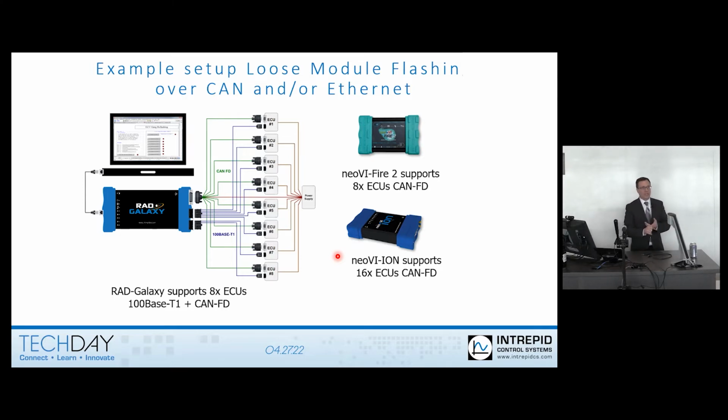So this is usually a case where all those ECUs are the same. You really don't have the ability to put them all on a single CAN bus because they all share a common diagnostic address. So in this case, what we have the capability to do is set this up to put each one of them on a different CAN bus, right? That way you can isolate them and know which one you're talking to based on which CAN channel you're working with.